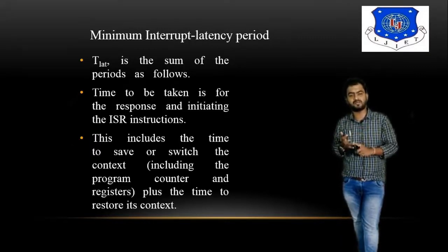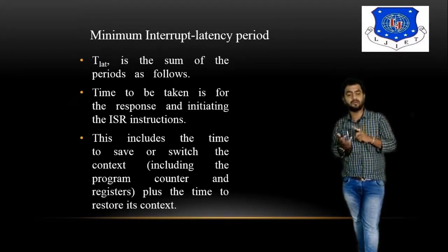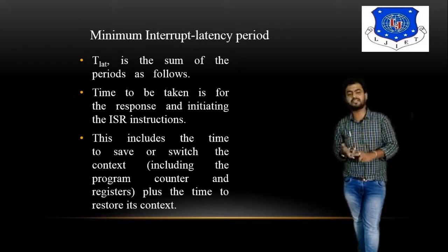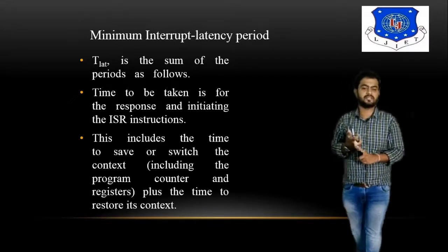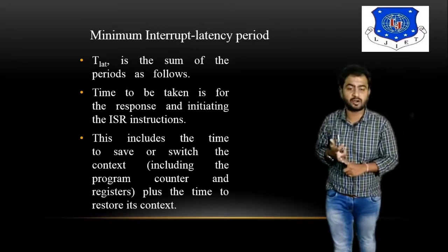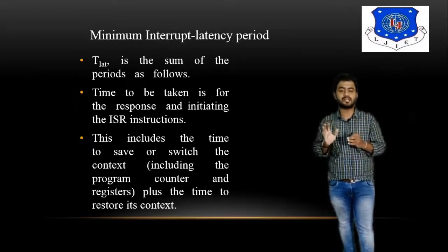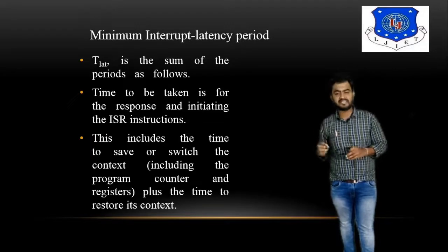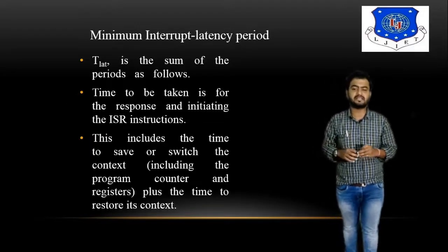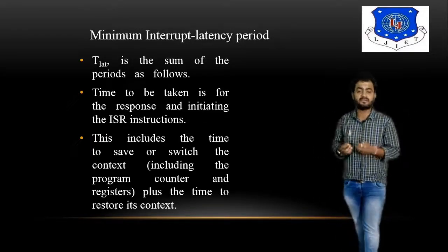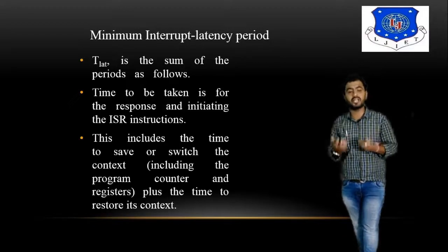We have to wait for the input. If it comes, then we have to read it. After reading it, we have to decrypt it. After decrypting it, we have to encode the data. After encoding the data, again we have to send a signal back to task A, or the call function 1. So minimum latency period means that ultimately we are talking about the period of the ISR execution, the counter register time, and the storage time also included.